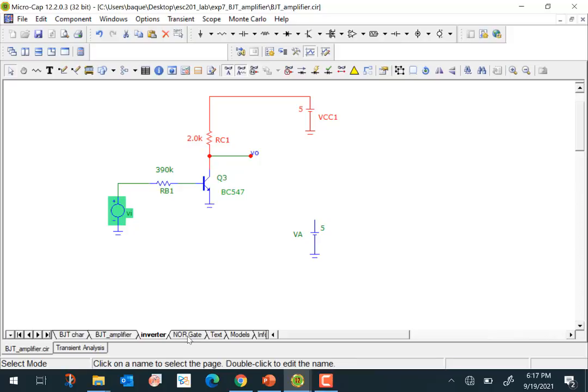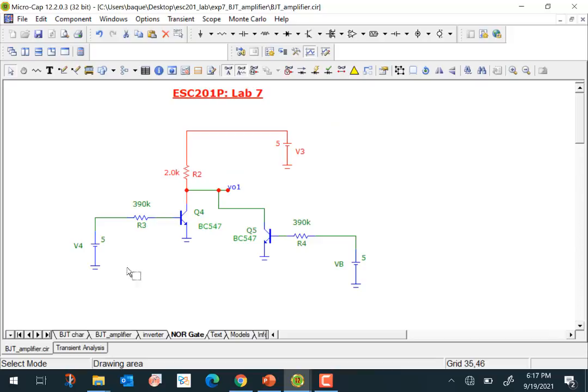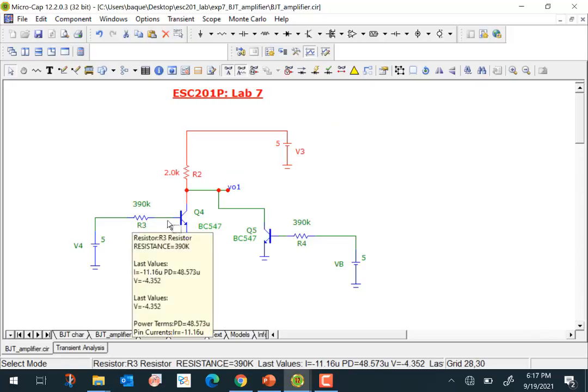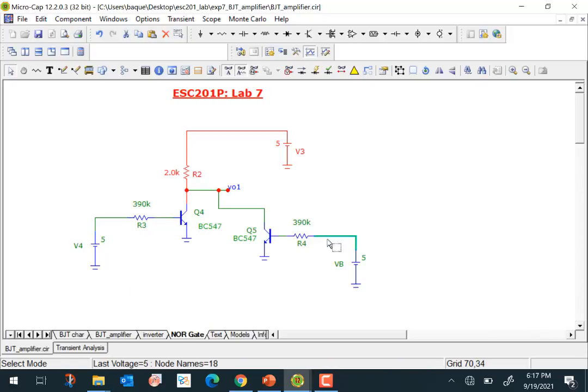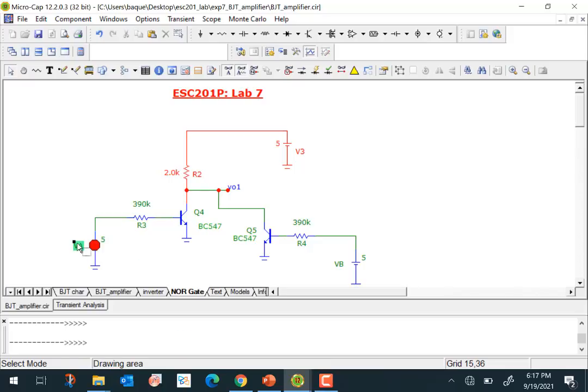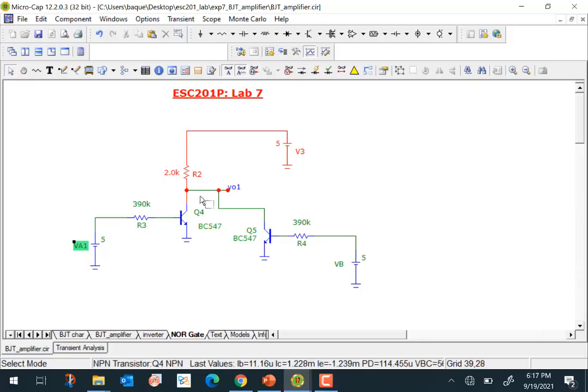The next thing that you could do is, once you have an inverter, you could take two such elements here. So this is one and this is the other one. And you could connect them in parallel and you can create a NOR gate here, right? So two inputs are there. Let's call this VA. Sorry, I guess I have defined A somewhere else also. Let's call it VA1. All right. So there's an input VA1 and there's an input VB here, right? And this is the output here. And so what we are saying is that this is a two input NOR gate here.